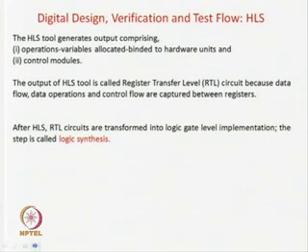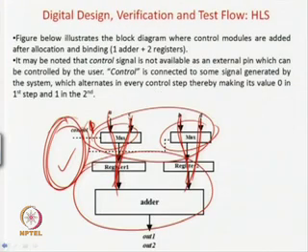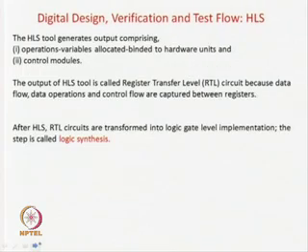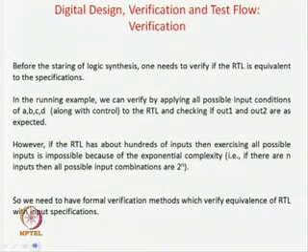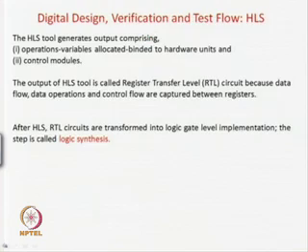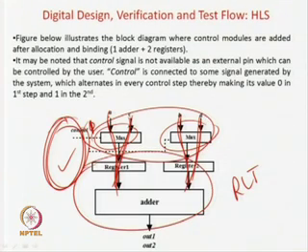So, in logic synthesis what do you do? You have to convert this, which you can also call the RTL level or architecture level, into gate level. So, how do you do that? We have already done this in our digital design class. Here you require registers, multiplexers and adders.